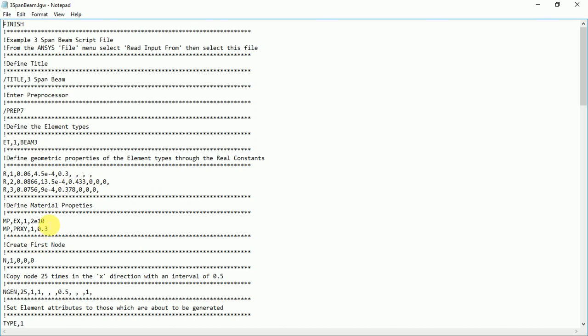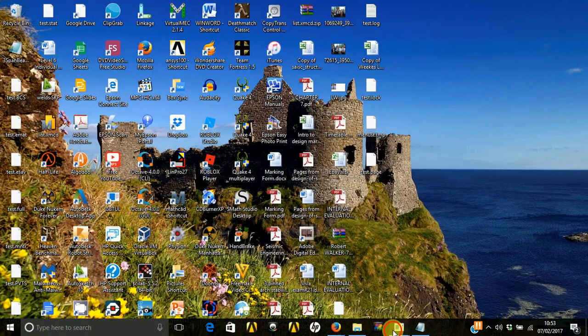If, for example, I want to change Young's modulus, I could have a variable called mod, ask the user to put that in, and instead of where I've got 2e10, I could have mod, and then that would obviously take in that parameter. But I think I need to explain that more thoroughly in another video. Okay, so the other thing I want to look at now is to add gravity to this model.